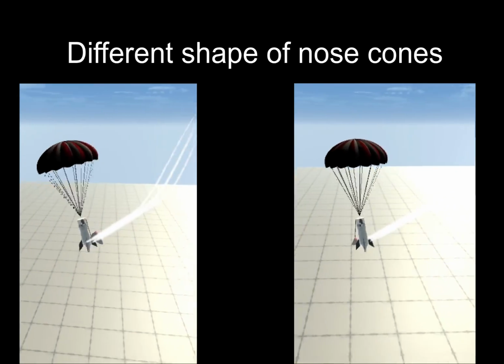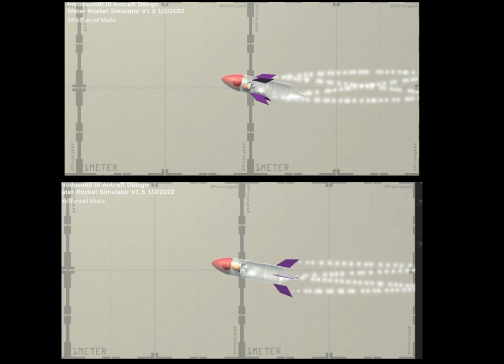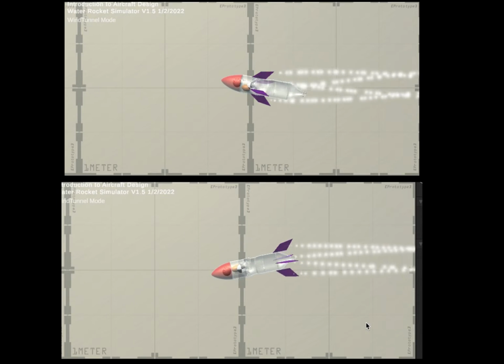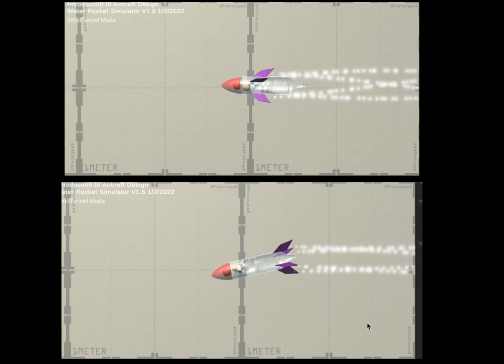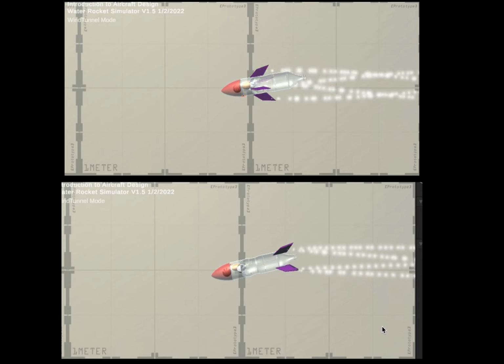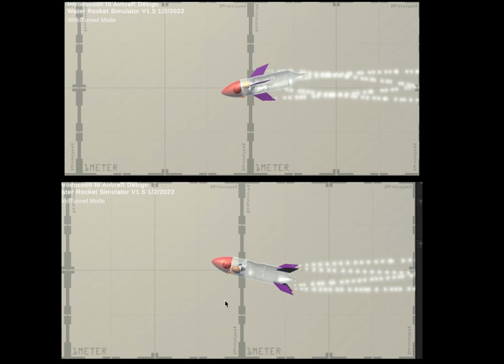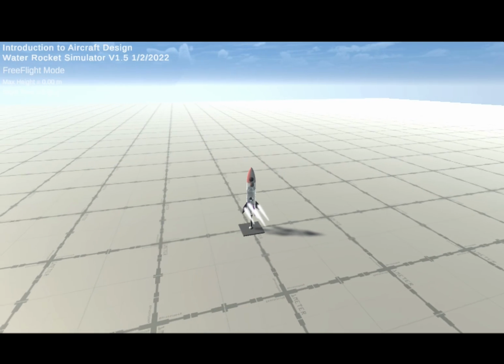To conclude, during our project we learned a lot while designing our rocket. During our integrated design phase, we looked into the aerodynamics and center of mass and how they have an effect on the flight time of the rocket. We also learned about the positioning, length and number of fins, and how they all have a significant impact on the rocket's flight as they control both direction and stability, but also have an effect on the rocket's center of mass and how much drag it faces when it flies.